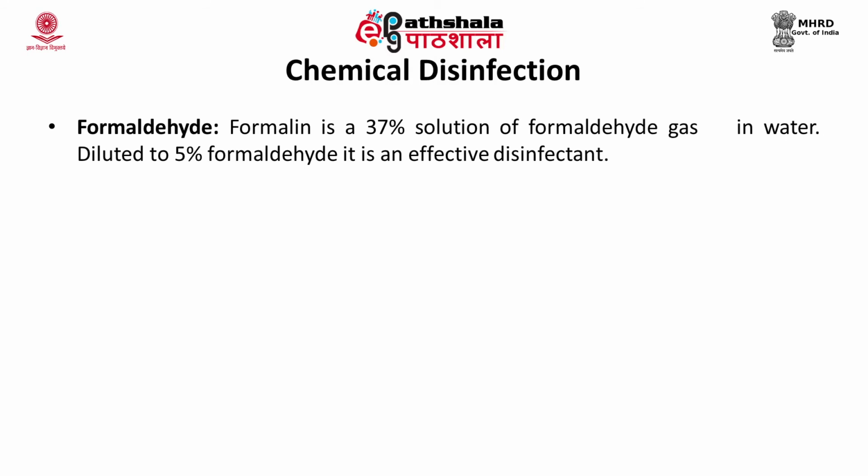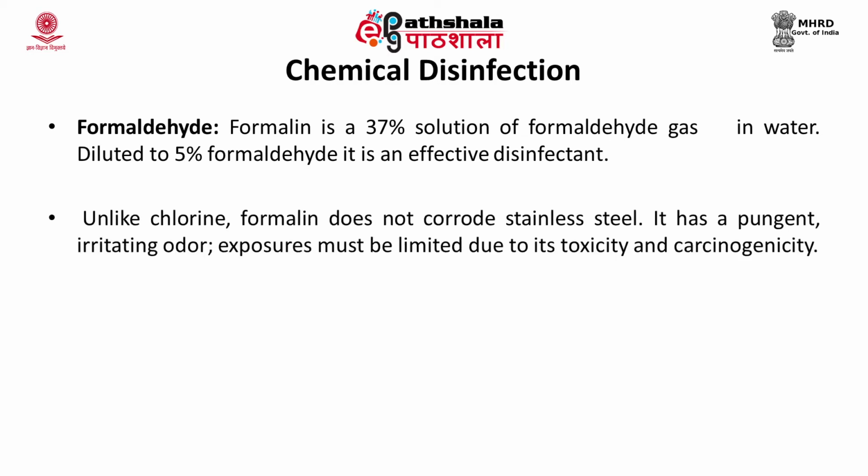After glutaraldehydes, the another kind of aldehydes which are used as the disinfectant are the formaldehyde, which is also known as formalin, and this is a 37% weight by volume solution of formaldehyde gas in water. Diluted to 5% concentration, it is an effective disinfectant, and even at 0.2 to 0.4 concentration, it can inactivate the bacteria and viruses. Unlike chlorine, formalin does not corrode the stainless steel, but it has a pungent, irritating odor. Therefore, the exposure must be limited due to its toxicity and carcinogenicity.